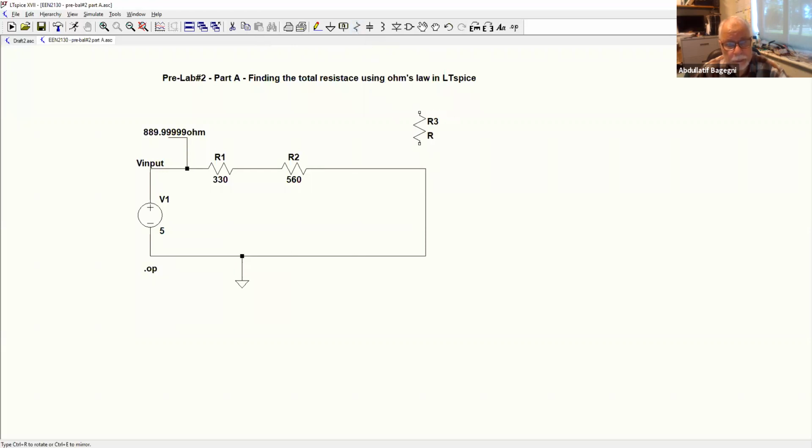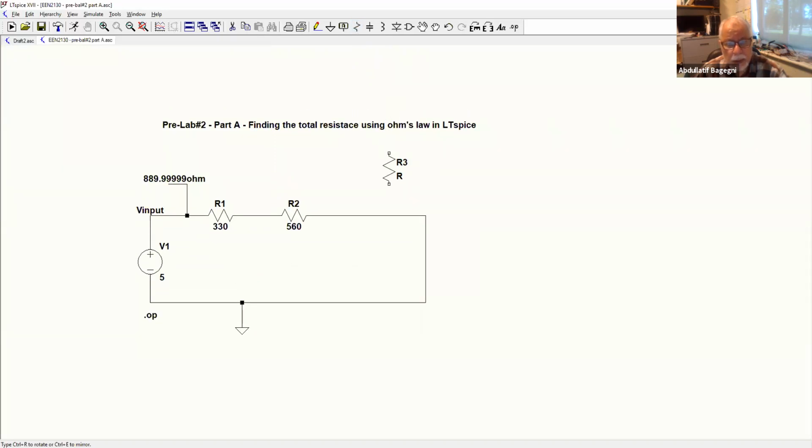Now, when I click on the resistance, I just release my hand from the mouse, and then Control R to rotate it one time, second time, three times, in order to get a plus, and then we place it anywhere. If you need to add another resistance, you could add it here, and so on.